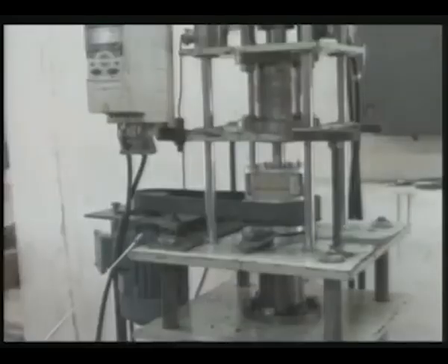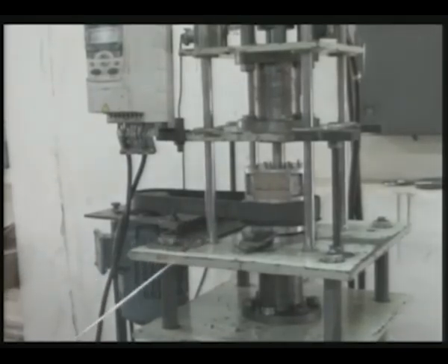The main problem of the MRFA process is non-uniform finishing of the workpiece, and also due to the reciprocating motion the abrasive particles come in contact in a straight line path. So to increase the finishing efficiency of the MRFA process and to uniformly polish the workpieces, rotational magnetorheological abrasive flow finishing has evolved. In the rotational magnetorheological abrasive flow finishing process, permanent magnets are used.